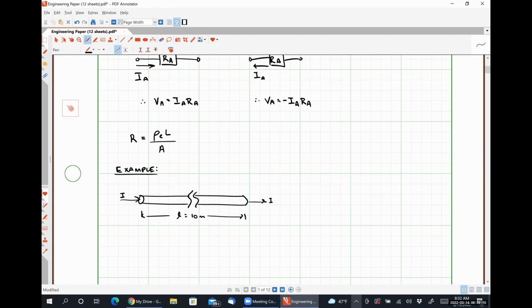And this piece of wire is what's called AWG number 18, which is very similar to the wires that were used in your jumper kits in all your engineering 120 series classes. AWG number 18 wire has a diameter D of 1.024 millimeters, and the copper conductor has a resistivity of 1.68 times 10 to the negative 8 ohm meters.